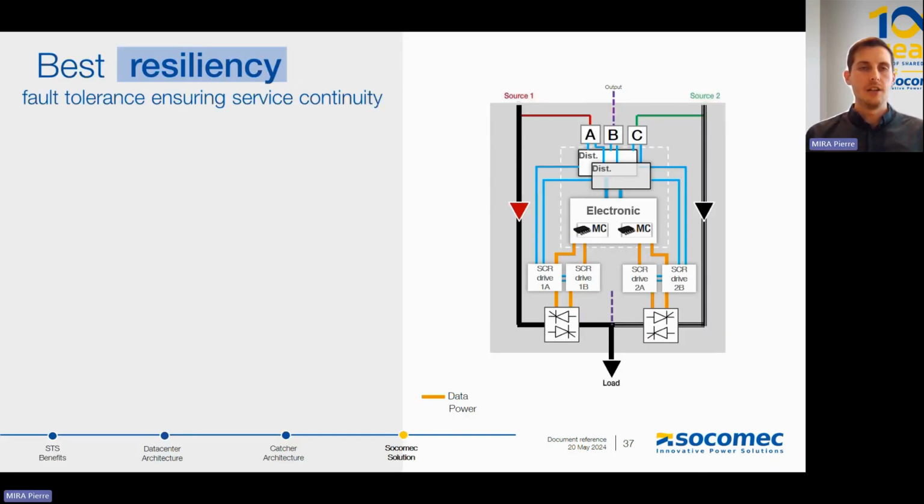To have this very high level of resiliency, I'd like to speak about the redundancy. Some people think STS is a single point of failure. However, it's not. STS is the last design securing the PDU, which is securing the load. So it's very important to have a very high level of resiliency inside a static transfer switch. Here in this example, we show the resiliency being very high from the redundancy of the architecture. Every single critical component is redundant.